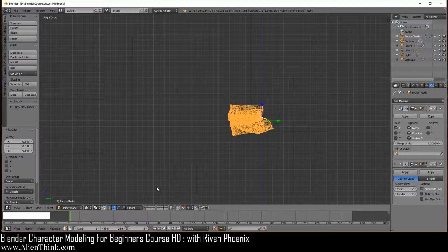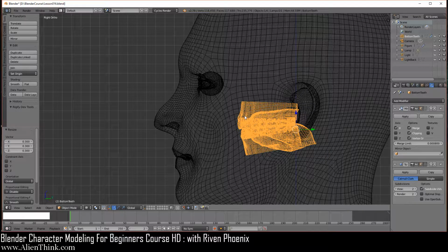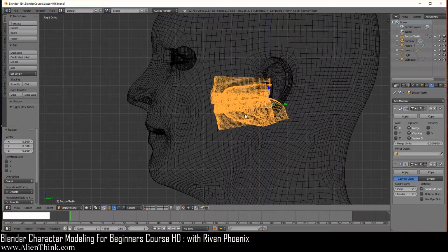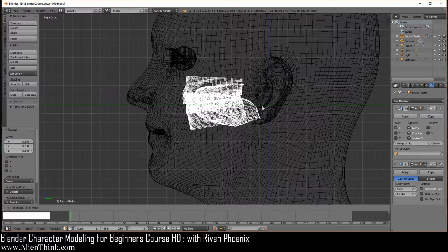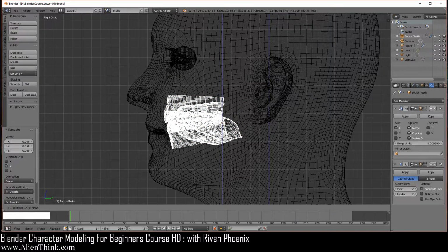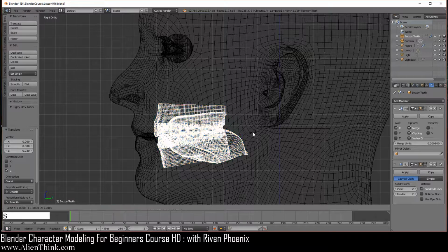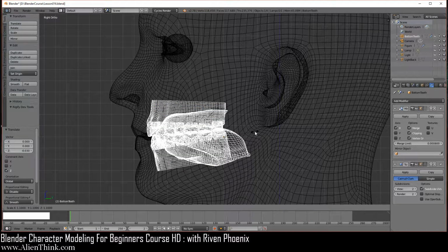This is where we're now going to shift and click on this layer over here. Okay, click it. So now you can see the figure. Shift middle mouse button, just pan over here. I'm going to take it to the left 1, 2, 3, 4, 5. Going to bring it down 1, 2, and then 3. And then I'm going to press the S key to scale, and we're just going to scale it 1 time over here. Left click to confirm.